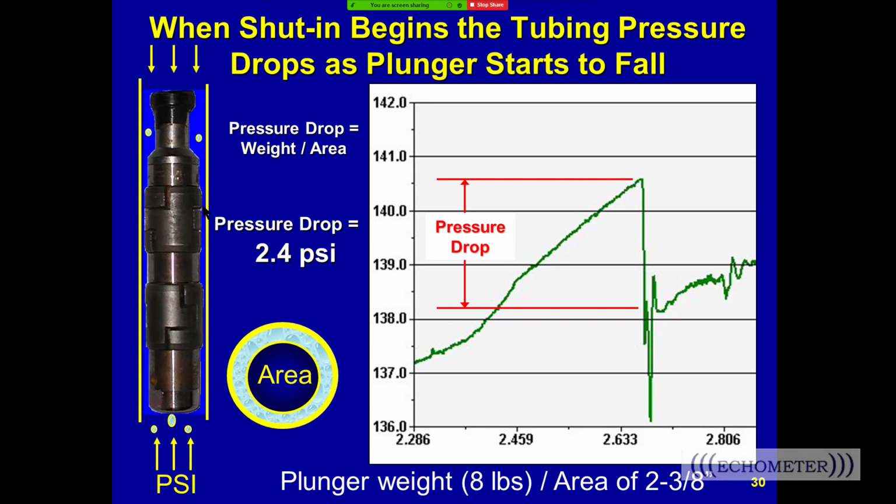So whenever you track a plunger with a gas gun, you have to charge the gas gun, if it's a remote fire gas gun, to an internal pressure greater than the maximum pressure you see in the well. So let's say your pressure goes up to 400 psi during the cycle, then you need to put more than 400 psi nitrogen pressure in the gas gun to keep the gas valve closed.